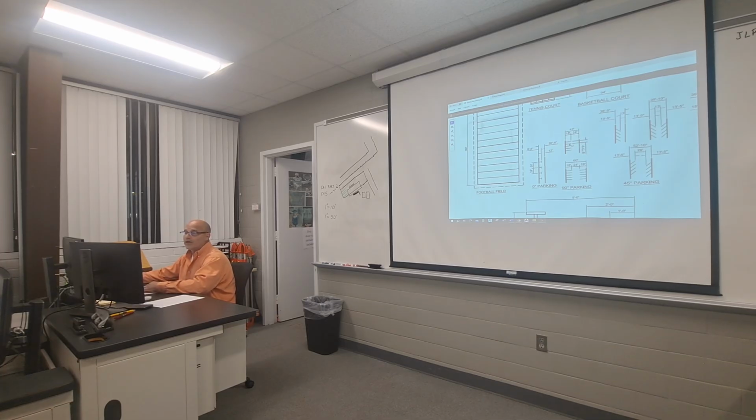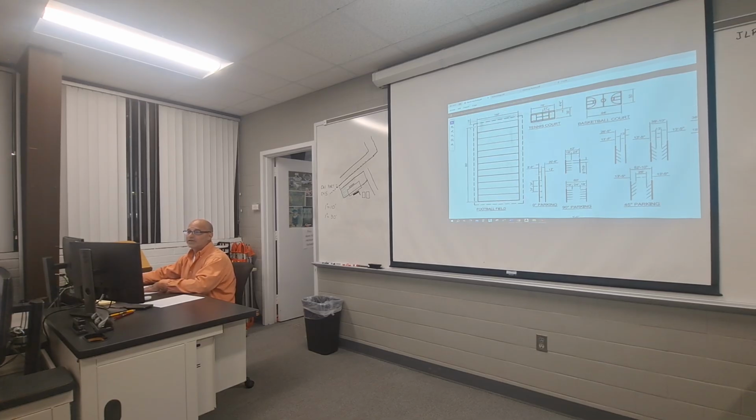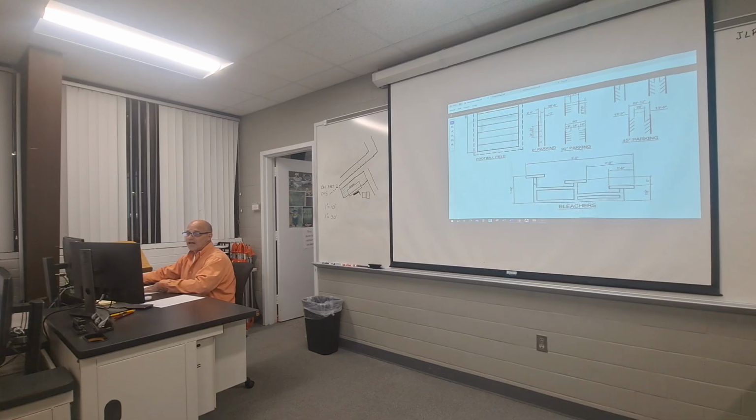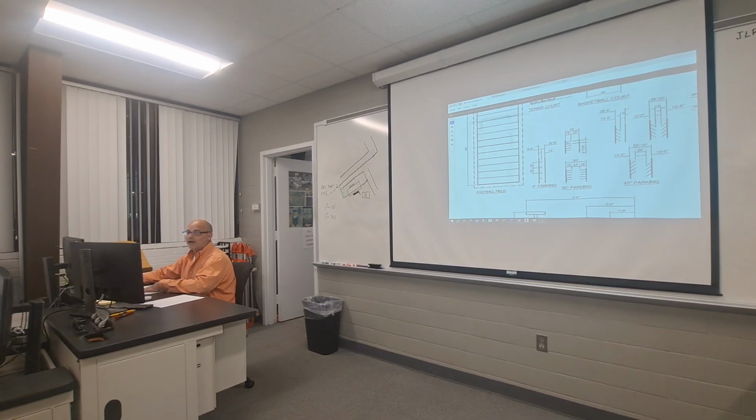You could make a layer called the paint layer that has like a 0.3, 0.2 millimeter line weight, something light, because object lines, edges of concrete, edges of sidewalk, edges around the football field, edges around the tennis courts, the outline of all of those are object lines. We're considering this just paint on the parking lot. So you will need to show all your parking spaces, but once again, you will not be showing dimensions. I will be measuring to see if they meet the dimension standards.